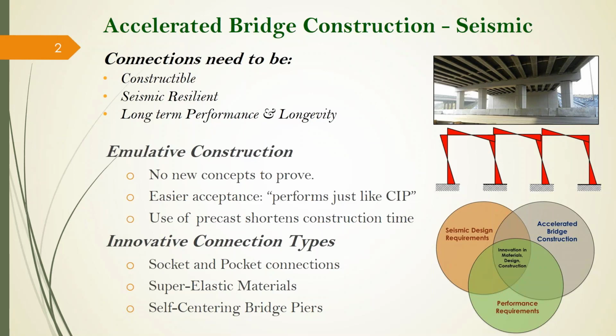As we talk about ABC and seismic, the connection is becoming the most important part, because this is within the load path of transferring the lateral forces into the substructure and foundation. So we want connections that are constructible, seismic resilient, and also have long-term performance and longevity.